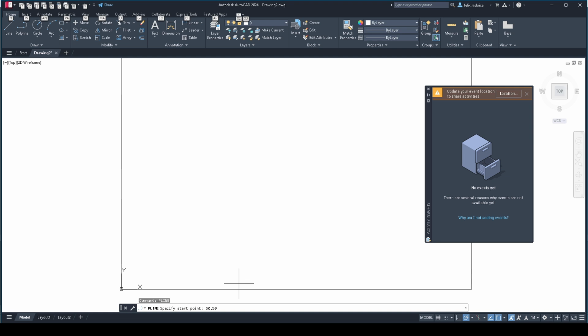then enter, and it fixed the first point. Now if I want to draw a 100 millimeter line like that, I have to figure out the coordinate. The single thing that changes is the x coordinate. So it will be 150 comma 50. Now it fixed the second point. This is a 100 millimeter line.